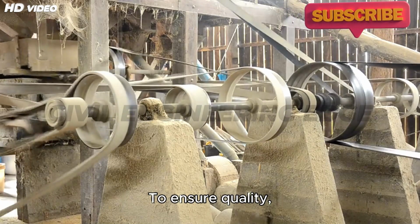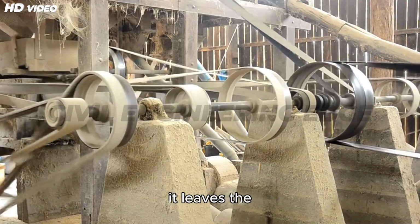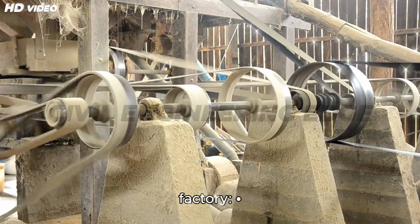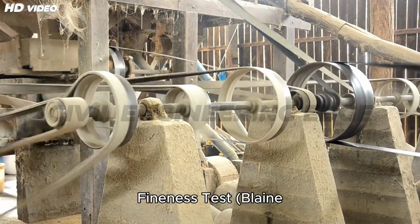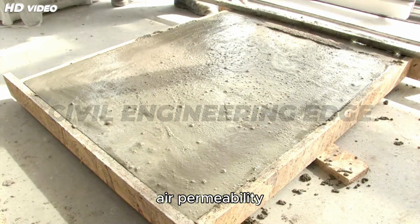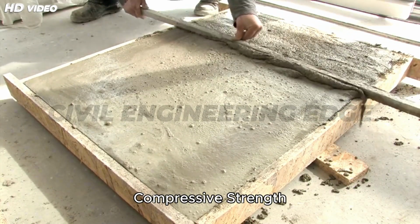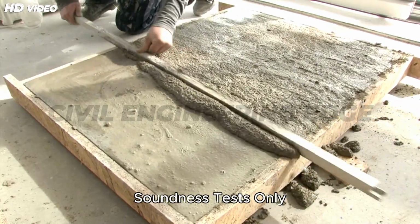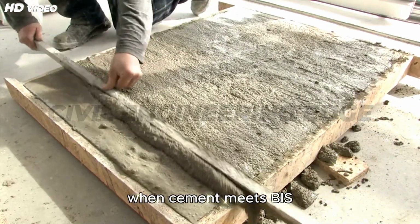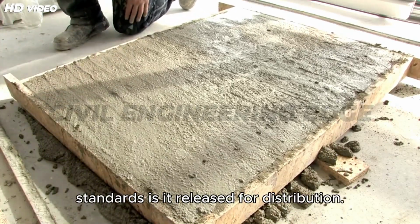To ensure quality, cement undergoes various tests before it leaves the factory. Setting time tests: initial and final. Fineness test: Blaine air permeability method. Compressive strength test, consistency and soundness tests. Only when cement meets BIS IS 269 or IS 1489 or equivalent standards is it released for distribution.